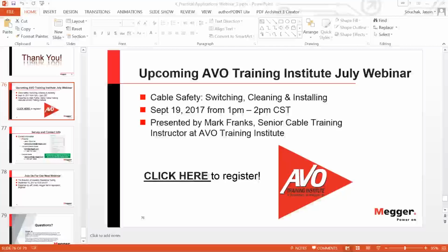So those type of things. If your tan delta test comes back bad, don't automatically jump to replacing the cable. Take a look and see if there's something you can do to improve those numbers before replacing the cable.